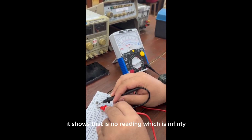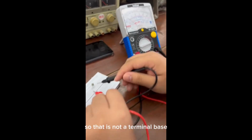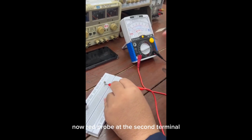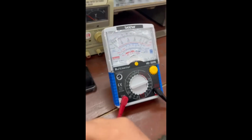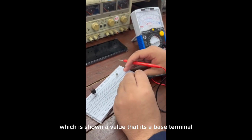It shows there is no reading, which is infinity. So that is not the base terminal. Now, red probe at the second terminal and black probe at either terminal 1 or 3, which shows a value, so that is the base terminal.